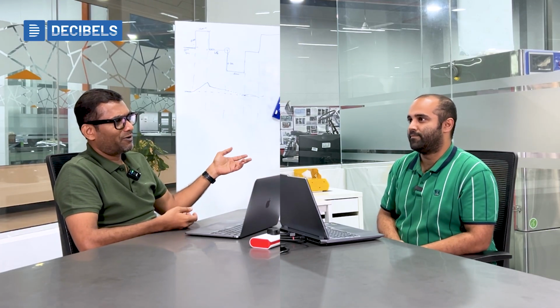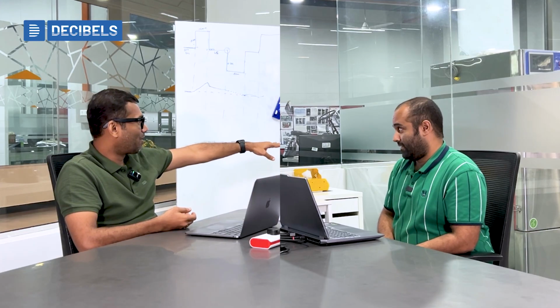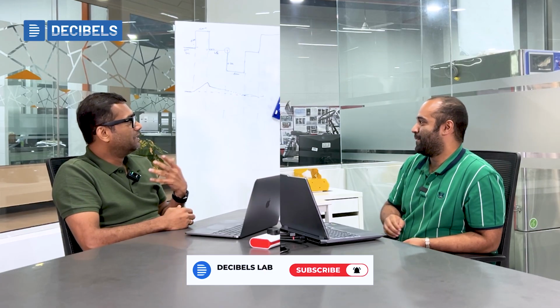I think this is a 48 volt system. Yes, a 51 volt system. That means you're probably drawing about 20 amps of current, still at about 1% SOC. That means they have 14 cells in parallel in this model, so about 1.3 amps of current for each cell. That means it's operating at about 0.2 C even at 1% SOC. Interesting, but that's how we can dig deeper.